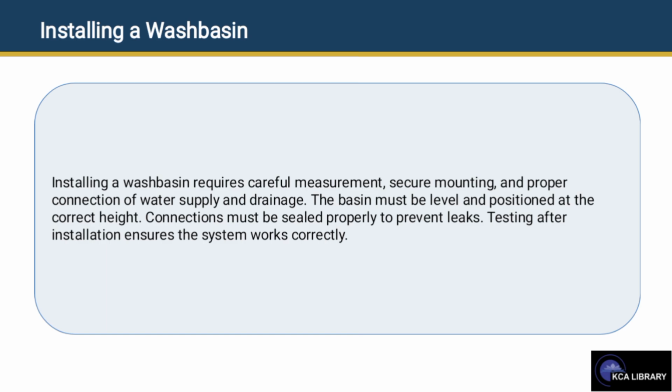So installing a wash basin requires careful measurement, secure mounting, and proper connection of water supplies and drainage. The basin must be level and positioned at the correct height. Connections must be sealed properly to prevent leaks. Testing after installation ensures the system works correctly.